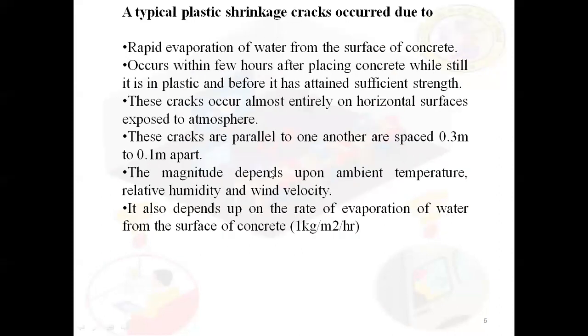Let us see what typically causes plastic shrinkage cracks. The reason to develop plastic shrinkage is rapid evaporation of water. The water which is stored on the surface of concrete will get evaporated. That is the main reason for plastic shrinkage cracks. Generally this occurs within a few hours, that means immediately after placing the concrete, due to evaporation or sunlight, the bleeding water will evaporate so that cracks will develop.